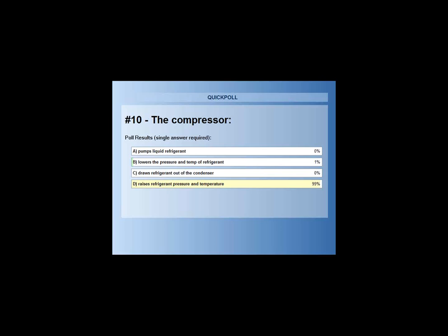His whole goal is to get the temperature to be hotter in the condenser than it was in the evaporator, and the way he does that is by bumping up the pressure. And if the volume stays fixed, which it does in this case because it's a closed cycle, then there's nothing that the refrigerant can do other than raise his temperature because I bumped his pressure up.